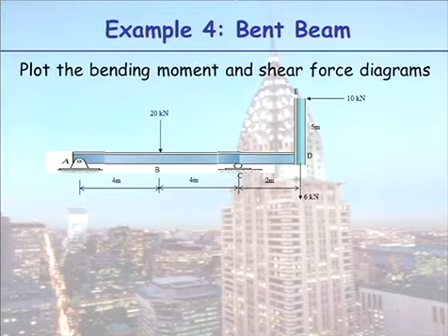I was just wondering, with this method of joints, it got to halfway in the quarter way, and it's already negative 960 kilonewtons. It just seems a bit excessive. Is that possible? How do you know? Because as soon as you get here, it's going to get to a couple of meganewtons. But is that what it's supposed to do? It's possible. I don't know how big your loads are, but it's possible. These forces are a lot bigger than this. And they get bigger as you move.